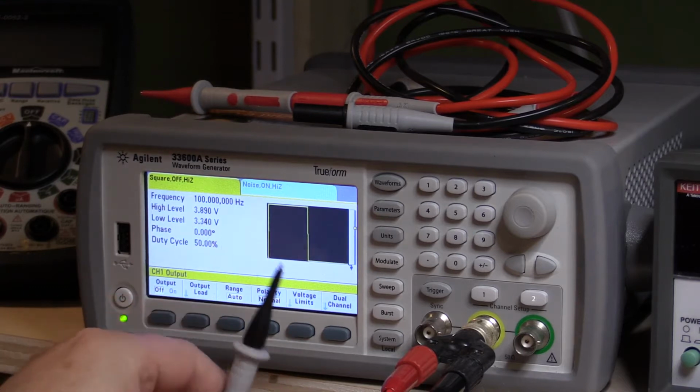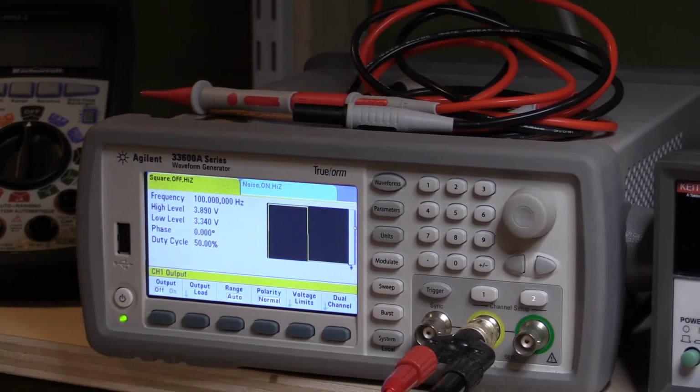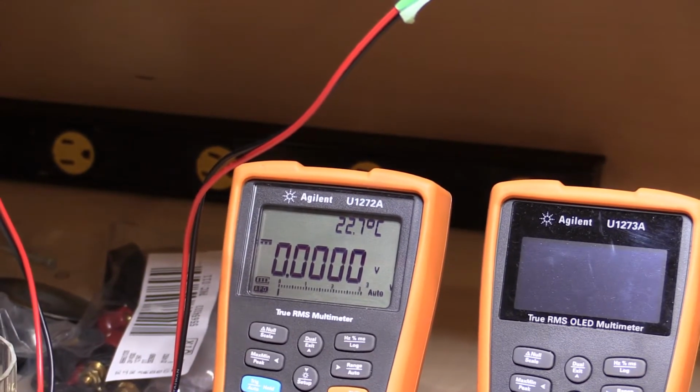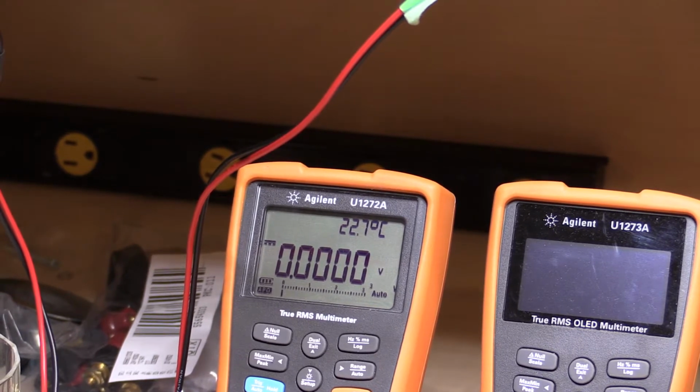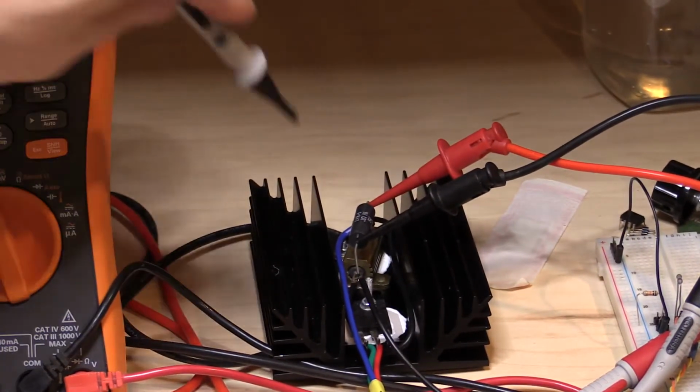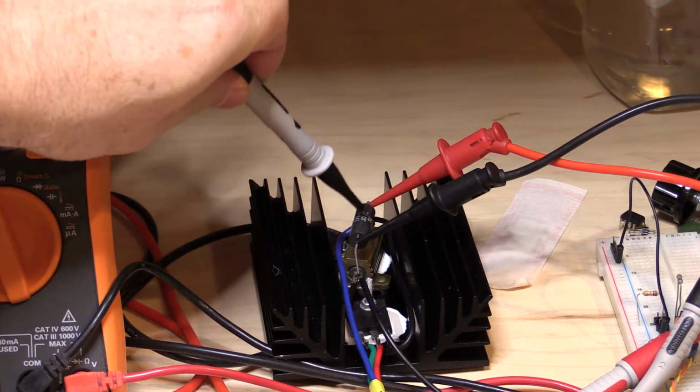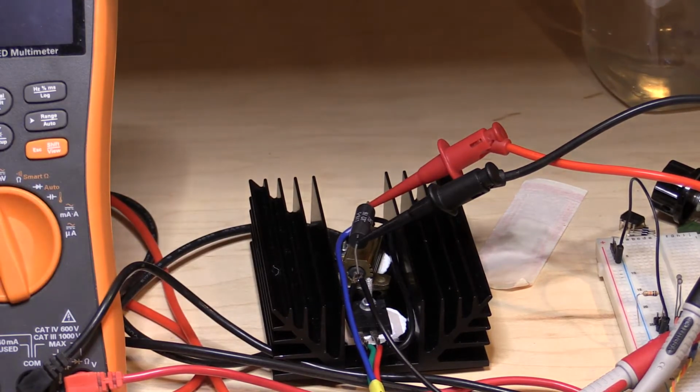So this with a square wave will pretty much exactly sweep us between the positive and negative limits that we want to test this with. What I'm going to have connected up to it is my Agilent meter, so it will read the average. So if everything's working correctly, it should be showing us 200 millivolts across our 0.1 ohm precision sense resistor, which is over here on the DC load. Right here it is, a 0.1 ohm 1% sense resistor.